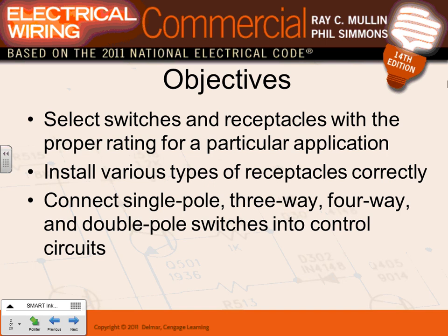I want to give you an idea. In a commercial building, there isn't a whole lot of 3- and 4-way switches, because of the energy code right now. When you get into the commercial building, the first thing you want to get out of your mind is 3- and 4-way switches. Cool? The reason for this is because we use occupancy sensors that, since people are moving, turn the light on to save energy, right? And also we use low voltage switching, which eliminates the need for 3- and 4-way switches. Can I have a thumbs up? When it comes to commercial buildings, 3- and 4-way switches, not a whole lot used.